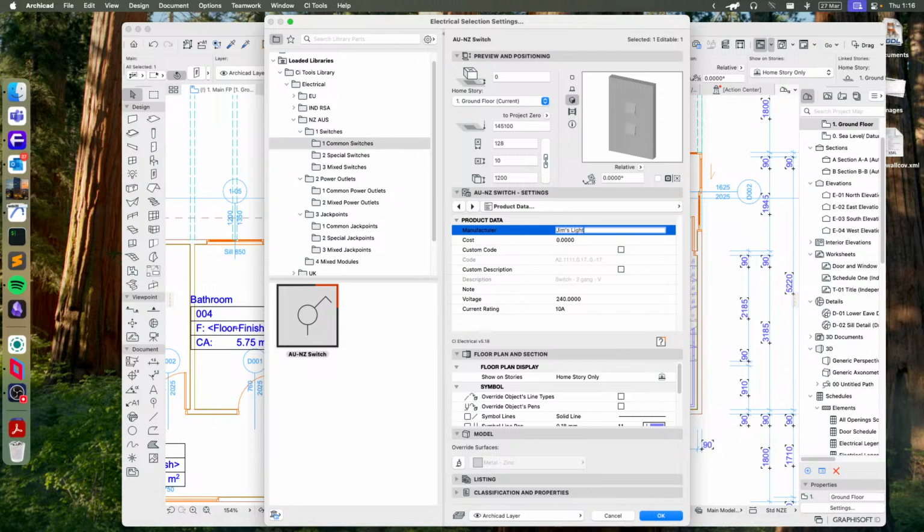Just a reminder, go into the interactive scheduler, hit scheme settings and hit the import button. Then we want to go to ArchiCAD 28 or whatever version you're in, CI Tools Extras, and bring in the legend and schedule, and then further customize them based on that. Pop them into your template, whatever you want to do. And you can control all of that in here.